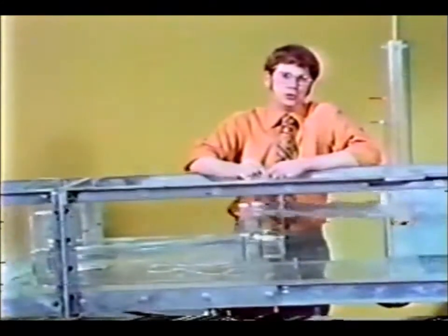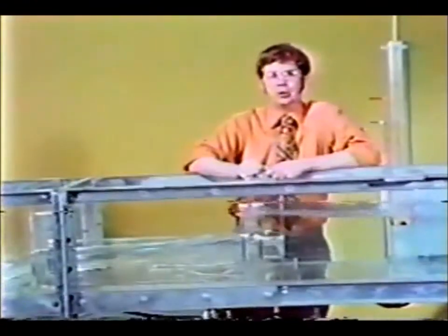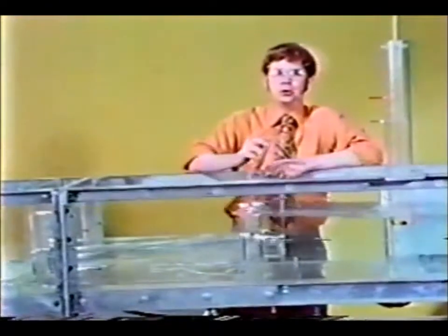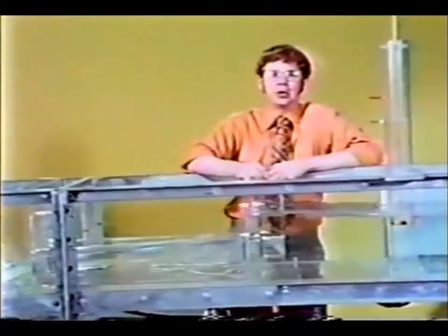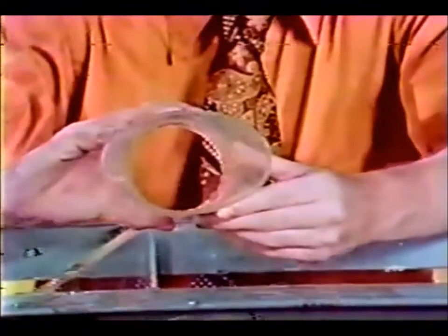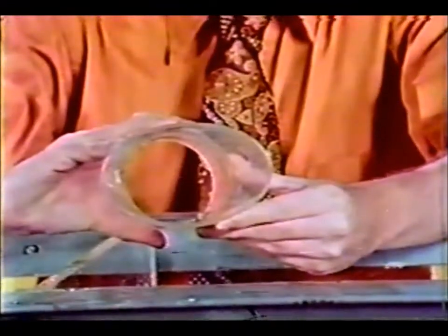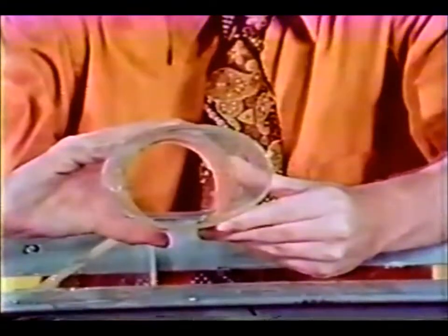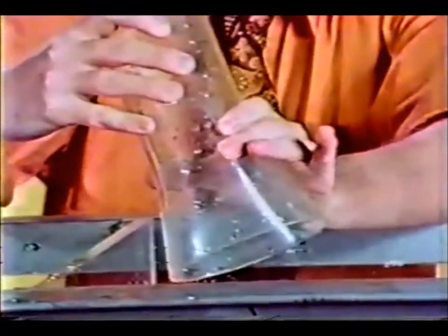All of the inlets that we have looked at so far have improved culvert performance. The beveled inlet, however, is termed an improved inlet. There are 2 other improved inlets that we'd like to look at: the side-tapered and slope-tapered inlet. Since the barrel is the most expensive part of the culvert, inlet control should govern the design. The side-tapered entrance has 2 possible control sections, one at the face, one at the throat. Therefore, the face is designed so that it cannot control at the design discharge.